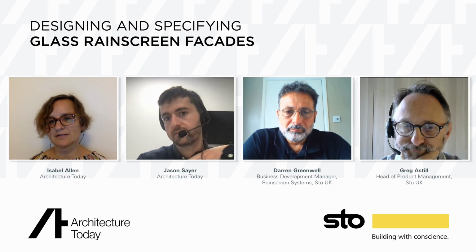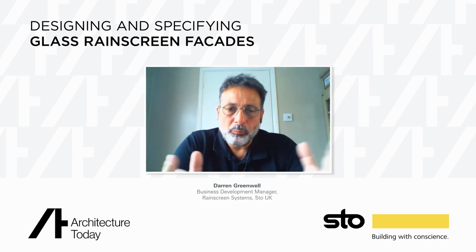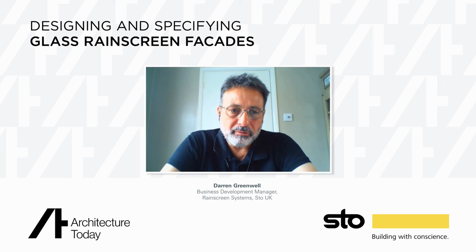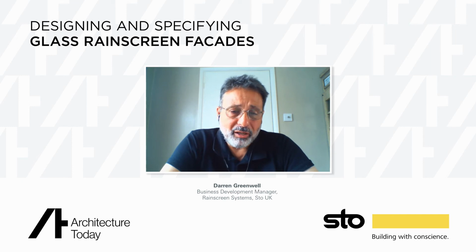Well, Darren, is that how long is a piece of string, or is there a rough guide? It is, if I'm honest. With everything commercial, it is very much how long is a piece of string. It's not necessarily the colour that adds the most impact onto the price of the glass. It's actually the size, the amount of cutouts, the edge detailing. It's once the wind load is calculated, do we need extra rails on the back? The colour has a very, very minimal bearing on the overall price of the system.